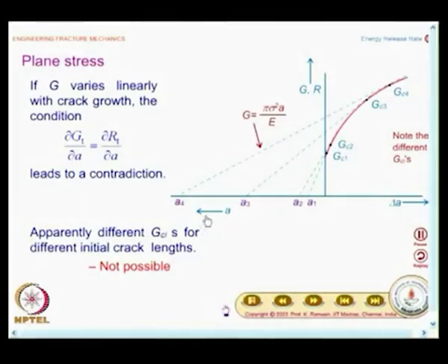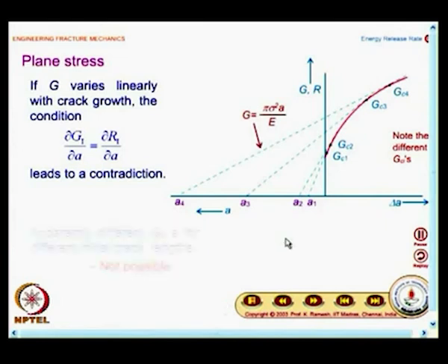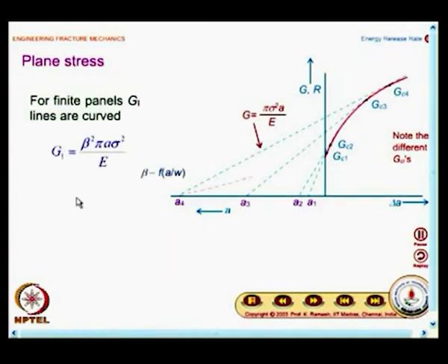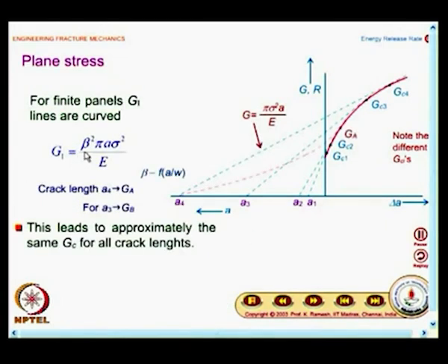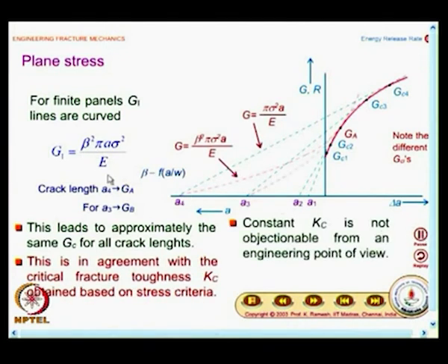You will have a basic expression for stress intensity factor and you will have a multiplying factor. On similar lines, as the length of the crack increases, I cannot have this as the expression. This expression has to be different. That would also be nonlinear, and you could label that as beta squared pi a sigma squared.